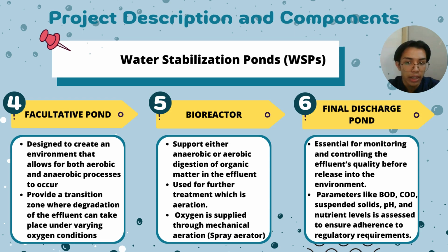The fifth one is the bioreactor. It supports either anaerobic or aerobic digestion of organic matter and helps in aeration. And the last one is the final discharge pond, essential for monitoring and controlling effluent quality before release into the environment.